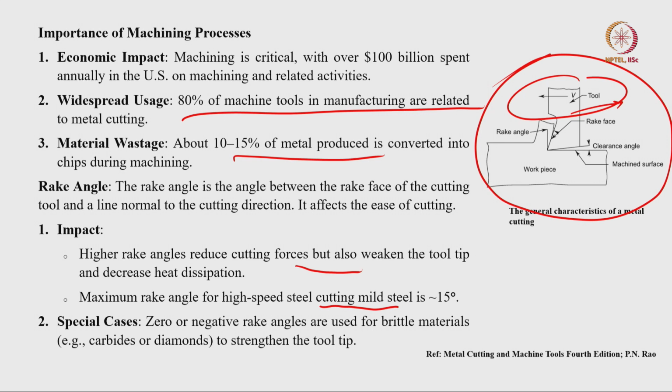So, you cannot just increase the rake angle without considering the strengthening of the tool tip, because otherwise it can cause tip fracture, which is not recommended. So, there is a limit to the rake angle that can be considered, and it varies from material to material.